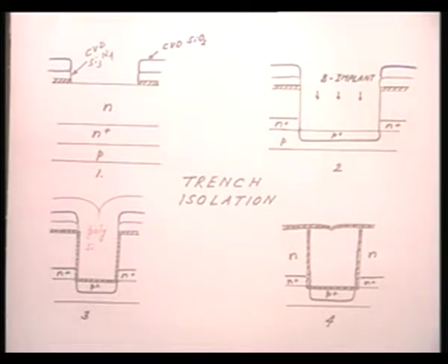Okay? So, we had a pad oxide, a silicon nitride and then a silicon dioxide, and then we have patterned this layer so as to expose certain region of semiconductor while other regions are protected by this layer of silicon nitride and silicon dioxide. Okay.